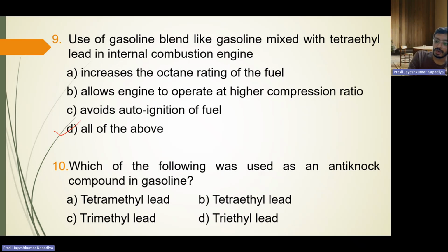Then one more thing is coolant water temperature. What will happen if you are increasing coolant water temperature? Less heat will be carried from the engine, which will increase the engine temperature. So knock will increase. One more factor is engine speed. To avoid the knocking in an SI engine, the engine speed should be higher. Then octane rating should always be as high as possible.